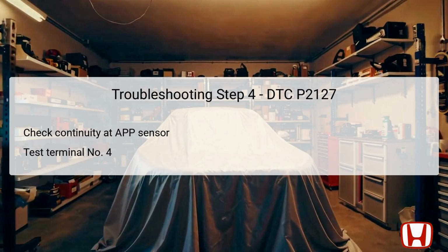A successful continuity test confirms that the electrical path is complete and indicates the APP sensor can correctly communicate its position to the ECM/PCM. Conversely, if continuity is absent, it signifies a potential short in the wiring between the sensor and the ECM/PCM, meaning further investigation is necessary.